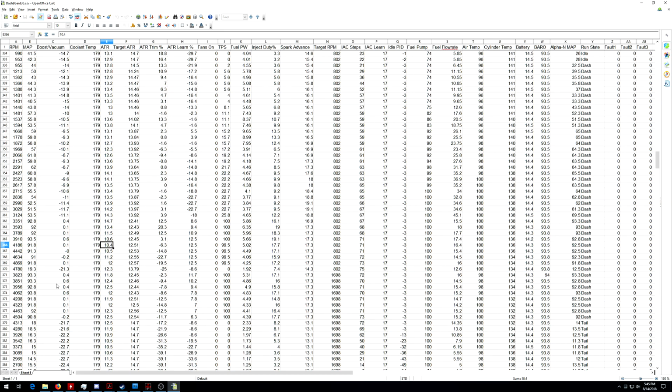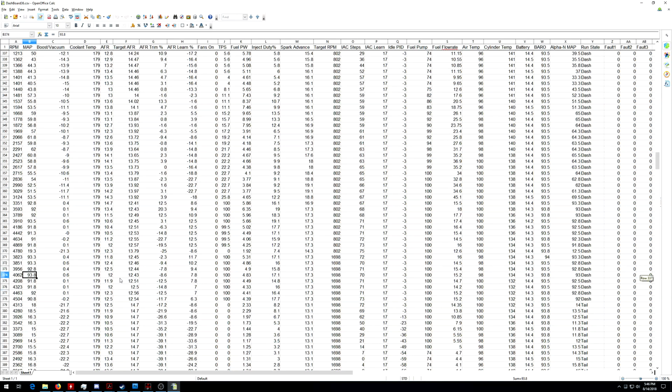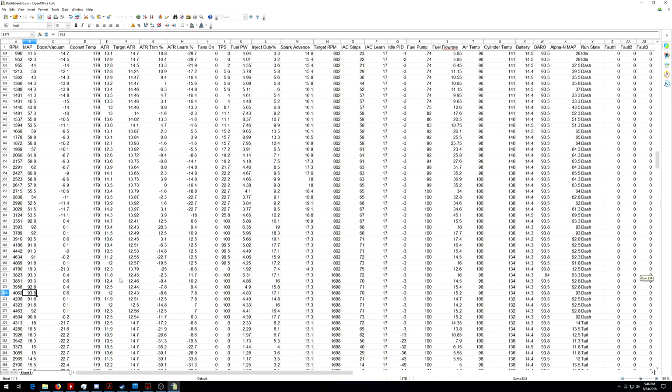Also, you can see the amount of manifold pressure. If you look on your FiTech unit, you'll see typically 45 kPa, 95 kPa, and at least if you have a power adder system like mine, it'll say 180 kPa for boosted systems, which is completely useless to me since I'm naturally aspirated. I don't even hit 95 kPa. I'm at about 94. So it's just something to keep in mind if you want to get some advanced tuning going on later on.